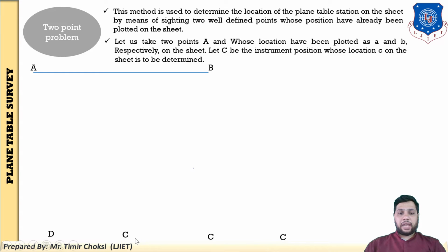I have deleted this particular C station. Here you have taken one auxiliary station as well as the imaginary station. Where you put the imaginary station, the angle CBD and the angle CAD should be neither too small nor too large. I will give an example.